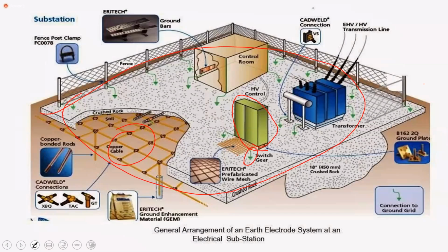Some of these things we just pass, but my purpose here is to increase your sensitivity to a number of things, so you won't just pass them anymore. All substations are fully fenced, and it's not just to keep you from thieving the equipment. The fence posts are all connected to the earthing mat.